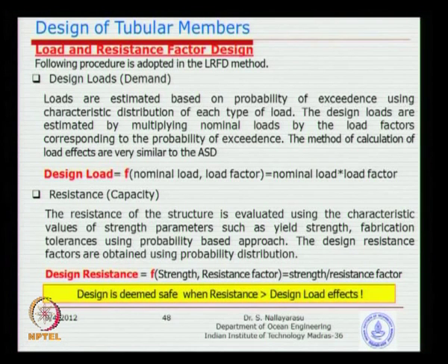That means we need to study each variable and look at its characteristics. You can go to the site, measure the wave heights for a period of 6 months, 1 year, 2 years, look at the distribution over time and the variations, and then extrapolate and predict what the characteristics could be over the next 100 years. So you can come up with the probability distribution functions for a particular location, and I think in your hydrodynamics course, hopefully they will teach you how to define a spectra for sea state conditions, which I leave there for now.